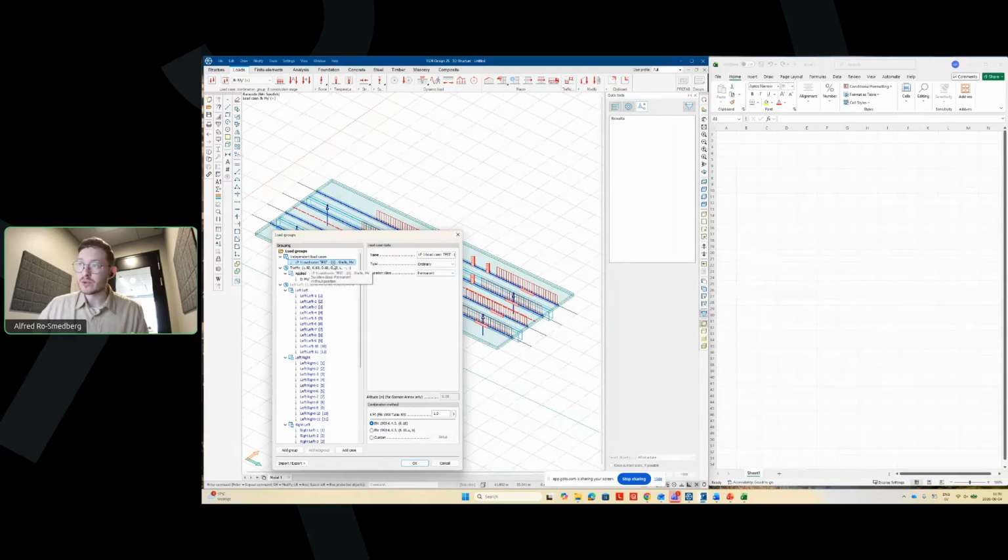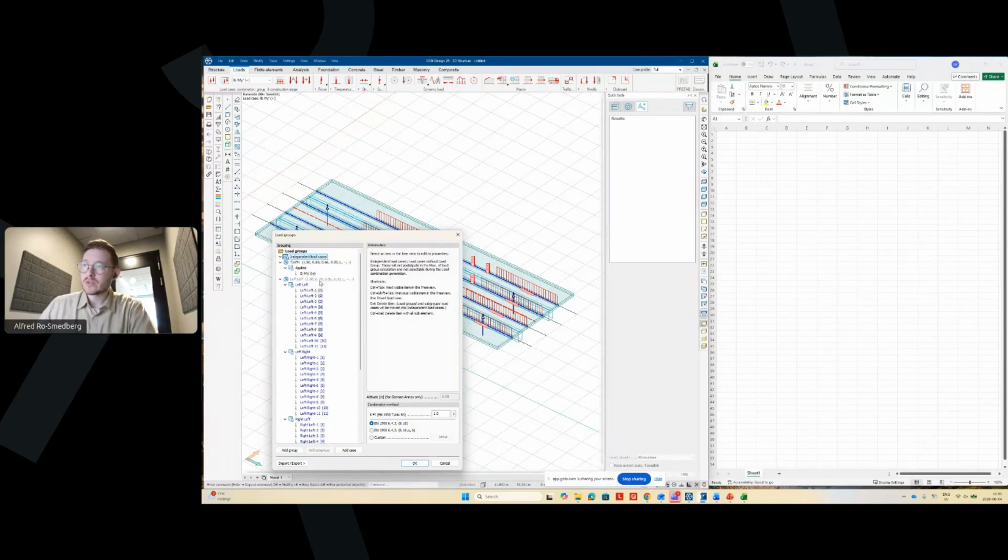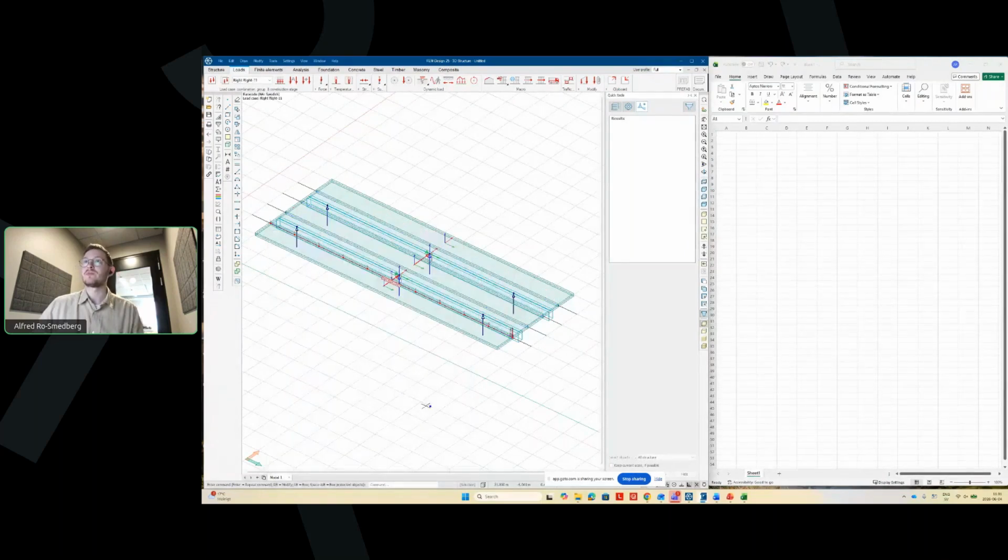And it's nice, it shows you what has been optimized. So here it was the shells result for MX that was optimized, but let's remove it for now. So now we only have the beam MY result. And then of course we have these unit load cases in the grids, which need to remain.